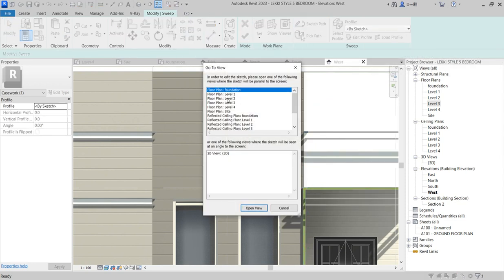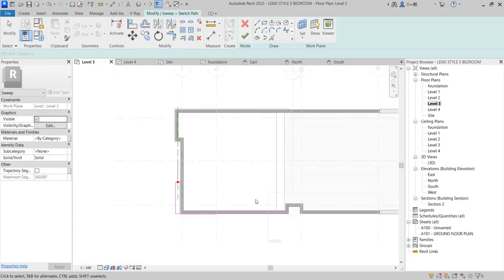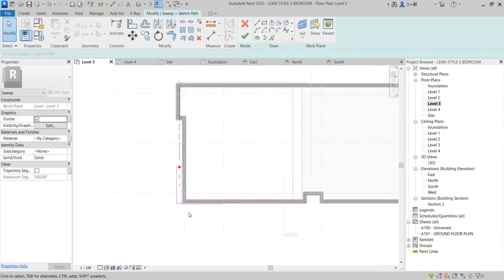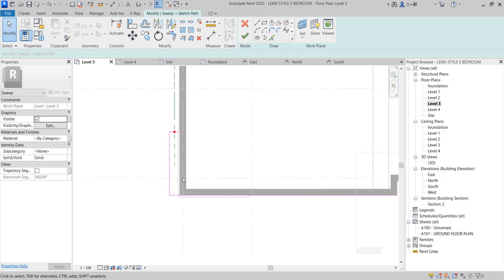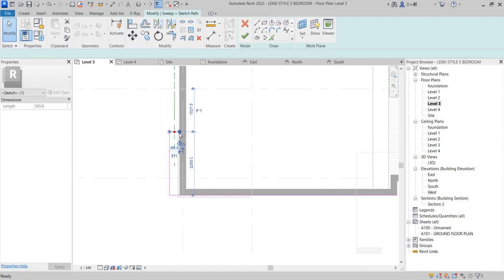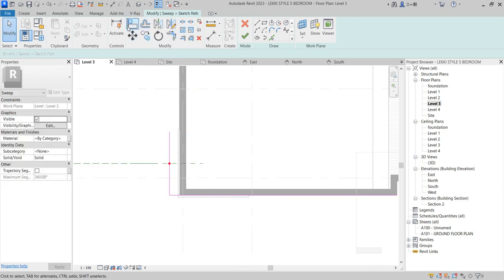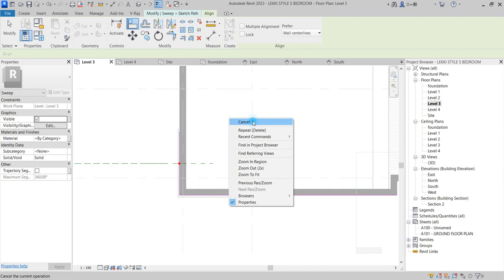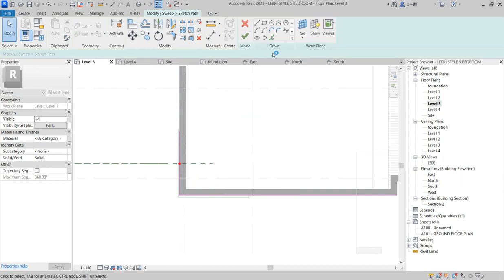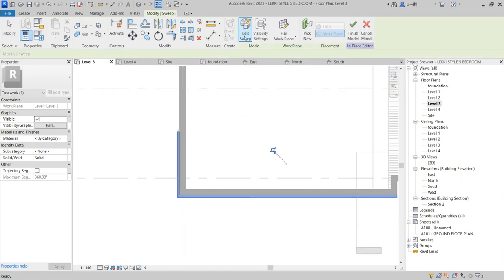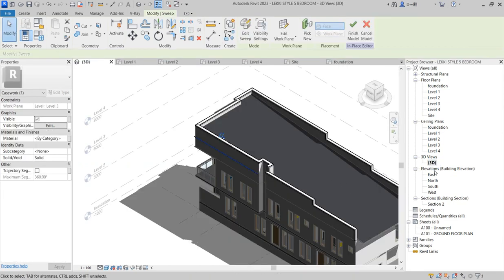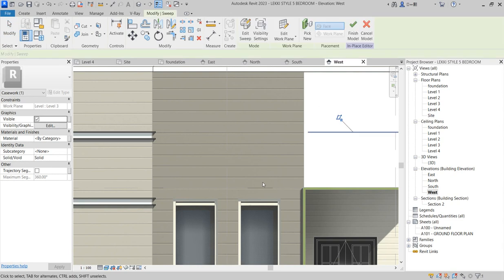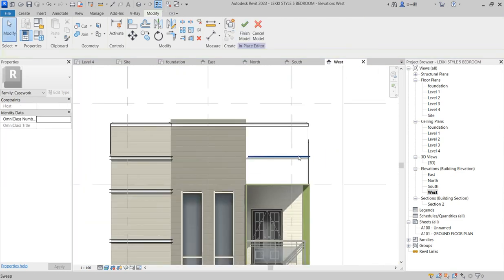part and go and select from level 3. So you align whatever you are doing to the original content of your design. So here you delete this and then you click align. So you are done with this, you click to finish and then you go to 3D and see what you've done. First go to rest and see that okay, this is added.